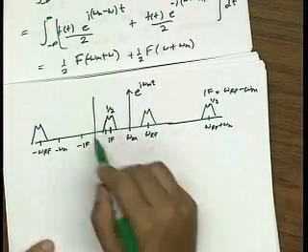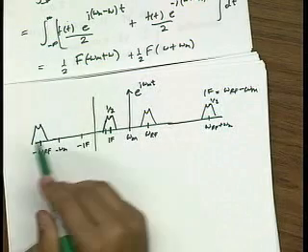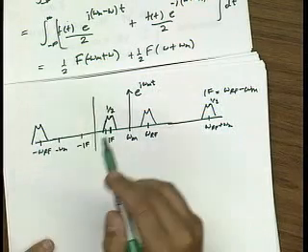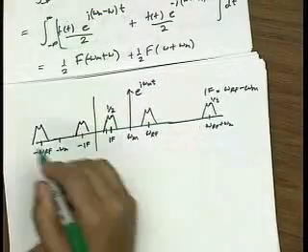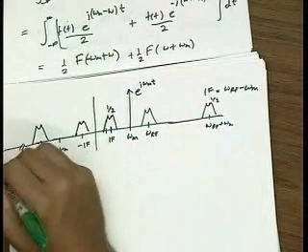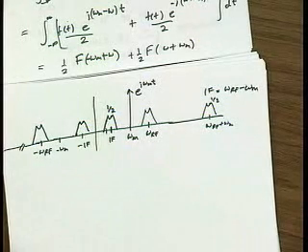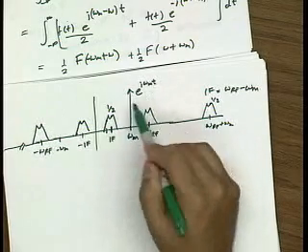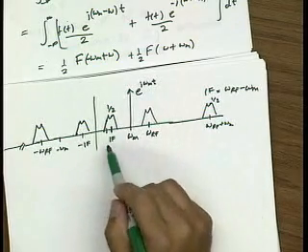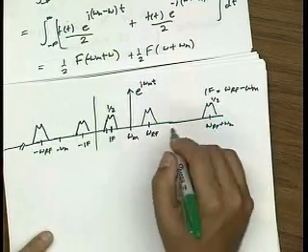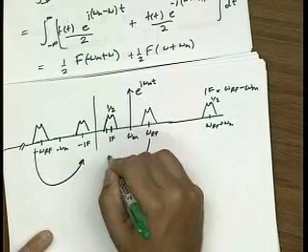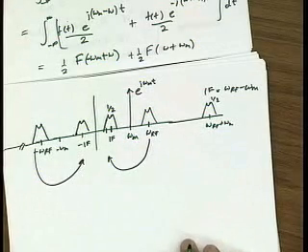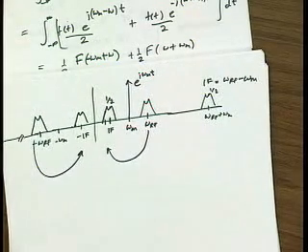And that's actually the desired down conversion, but because there's this negative frequency, I also have to take into account that I get a term which appears here and somewhere out here, which I won't draw. So just multiplying by one of these complex exponentials actually nicely does the trick. It moves my spectrum down to baseband. And what's interesting is that there is no image problem, right?